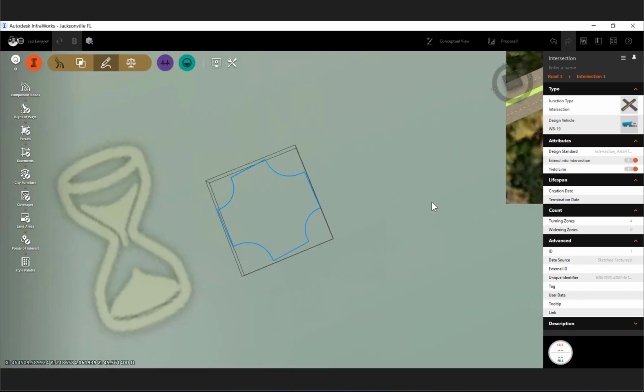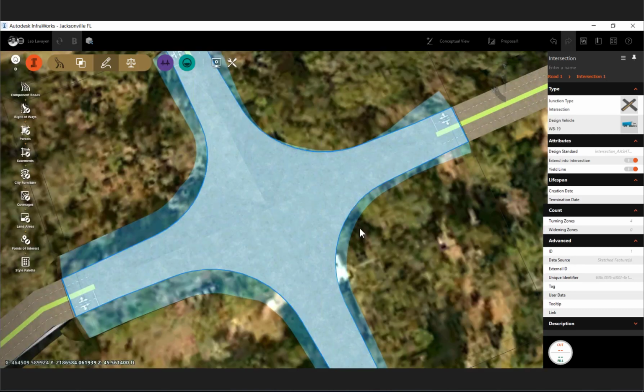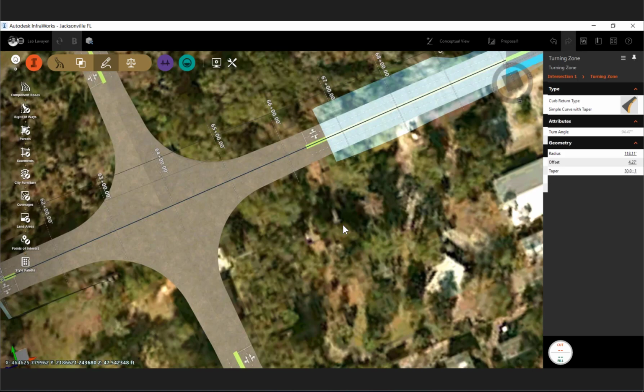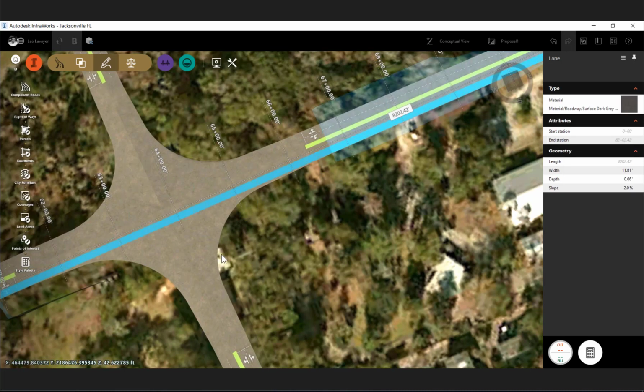Now, within Civil 3D, within InfraWorks, what I get is the ability of talking to these objects. Please note, as I select my objects and pick on my entities again, I get further selections. I can select my road, or I can start selecting the subcomponents within it. I'm not holding Control, I'm not holding Alt. That second pick on an element is really what drives a change inside of here. I'm not double picking, I'm selecting once, then selecting a second time, which has to do a lot with the way you work from within the software.